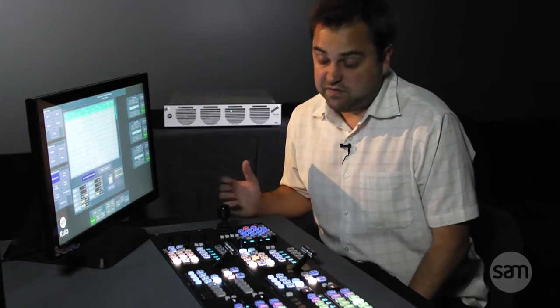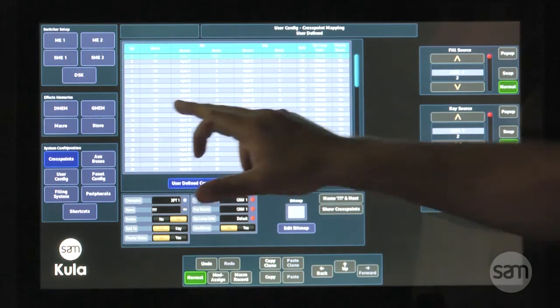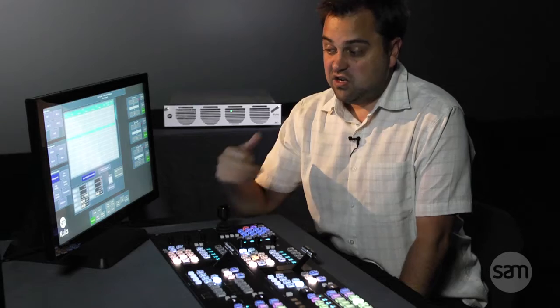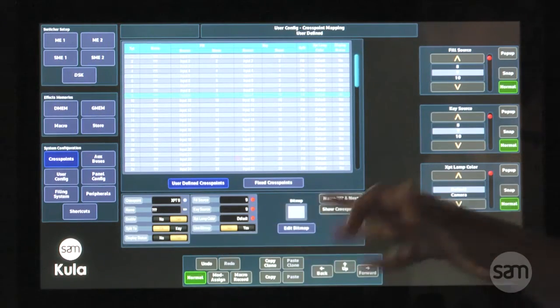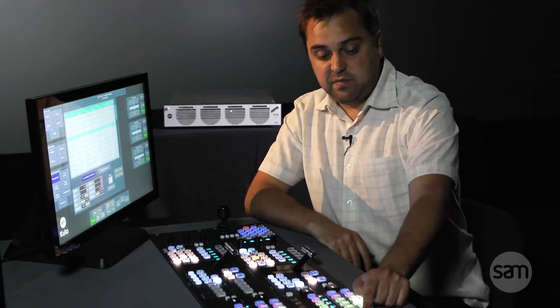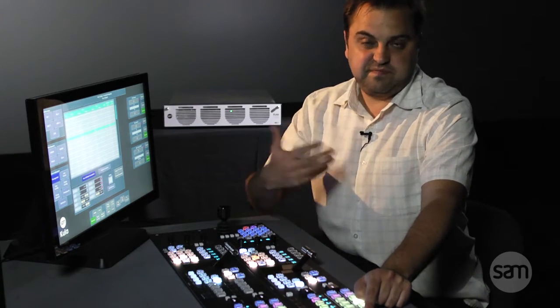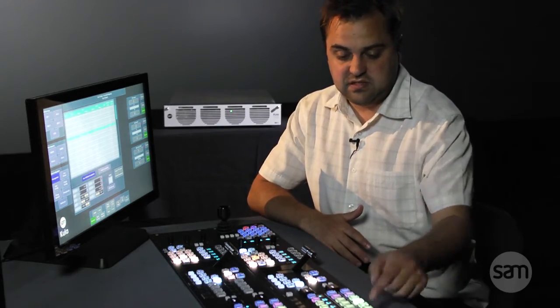Another handy feature for engineers, we feel, is a display status. Now I know, for example, crosspoint 9, input 9, I don't have any video on this. If I put display status to yes, then on my input 9, it's giving me a message, no video. So it's a good way of your users telling you if you lose any video.